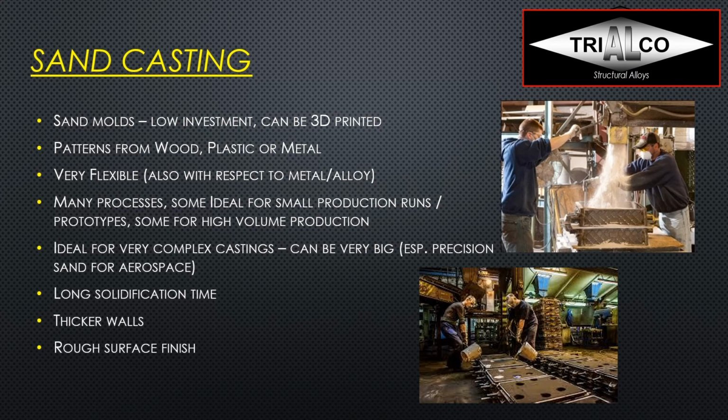You will also get less dimensional accuracy and have larger tolerances. That's of course something that helps you with hot short alloys, because when you get hot tearing issues in a permanent mold because the casting is restricted but wants to shrink, well, here it is a lot easier for shrinking metal to push the sand a little around, which leads to the downside of less dimensional accuracy.